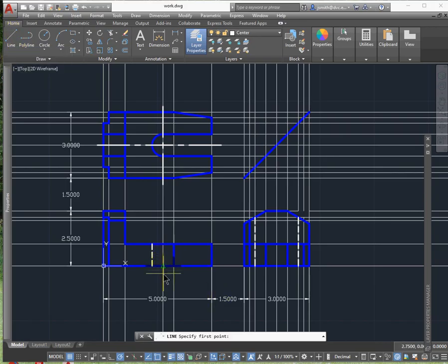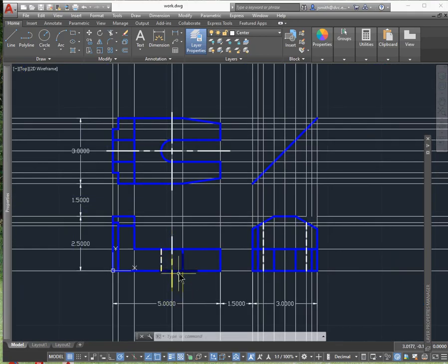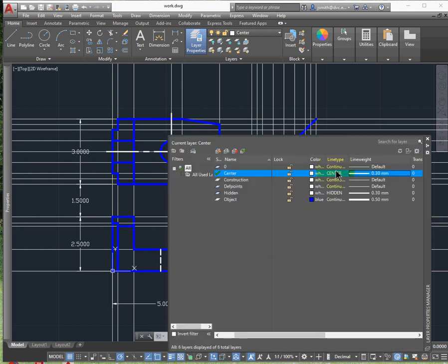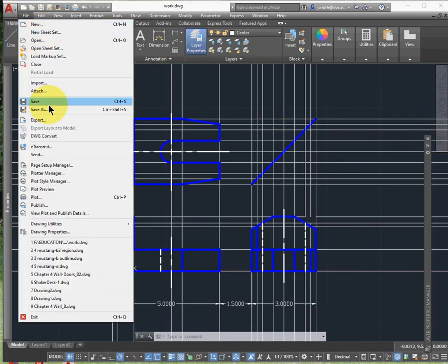And there's actually not that many of them. So I'm just hovering over, then I'm snapping. And if you don't see it when you hit escape, just make it a little bigger. Now, if you're in metric, this won't work. Sometimes people start building things in inches, thinking they're metric and vice versa. So that's usually the culprit. All right, so it looks good. I'm pretty much done here. So look at my line weight, and then we'll go ahead and print this out or plot this.